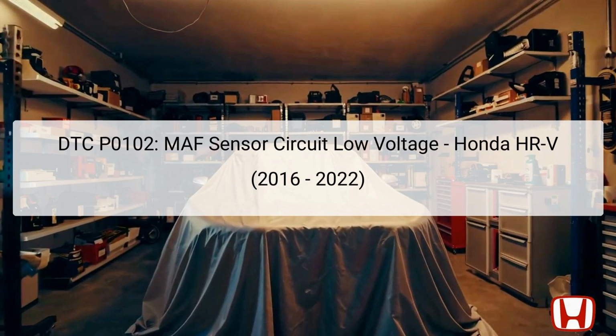The MAF sensor is located in the intake manifold upstream of the throttle body, where it accurately gauges airflow. When troubleshooting this code, ensure that general preliminary checks are considered before diving into specific diagnostics, as this will help in accurately identifying the fault.